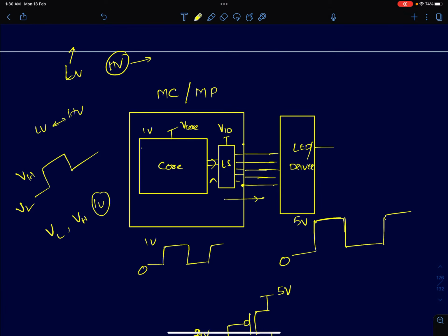Generally, we perform all the complex calculations and computations, and generate all the control signals, at the core level itself using the core devices, because core devices operate on the lowest supply voltages. Therefore, they give you all the benefits of technology scaling, right? Lower voltage means lower power, and you also get higher speed because of lower capacitances. So you reap all the benefits if you perform all the computations on the core devices. Finally, when they go to the external world, you just somehow change those levels.